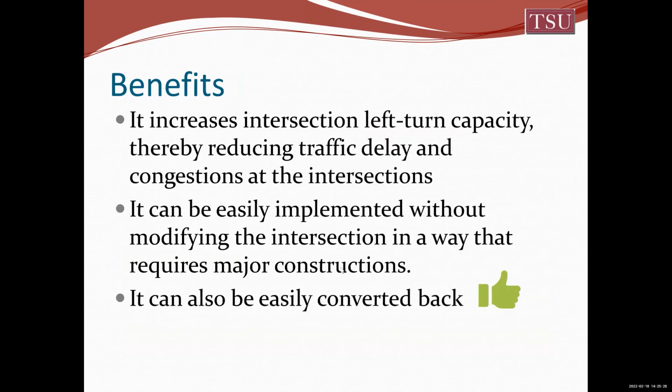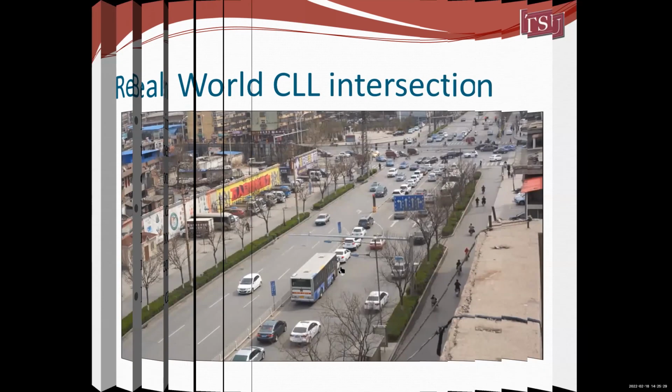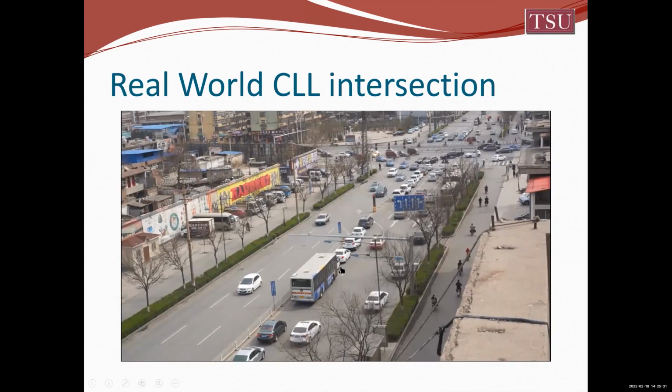Right. I have another question here from Kingsley. Exclusive left turns, like left-turn only, are typically used when you have more than 200 vehicles per hour. Is this method used where it is exceedingly higher? That's true. You can see from the case study I gave you that the left-turn volume is very heavy at certain intersections, so they exceed the capacity if you only give one left-turn lane. That's why they try adding another left-turn lane. That's the whole purpose of this design.